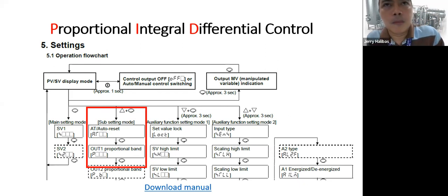So as the control valve moves up and down, opening and closing proportionally, there are erratic changes along the way. That's why you need to understand how to adjust manually. The output, particularly the temperature, is erratic.